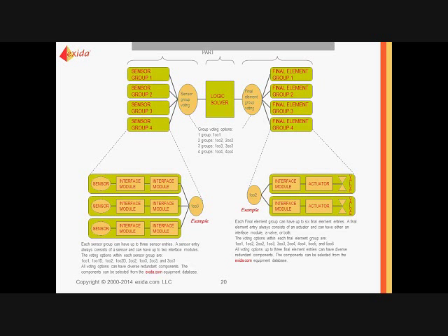And the components can be selected from the exSILentia equipment database. You can also put in your own failure rate data if there's a device, for example, that isn't actually listed in our database and there's a generic, but you actually have manufacturer's information, then you can certainly use that. It's a conscious decision by the user to do that. exSILentia allows you to do that.